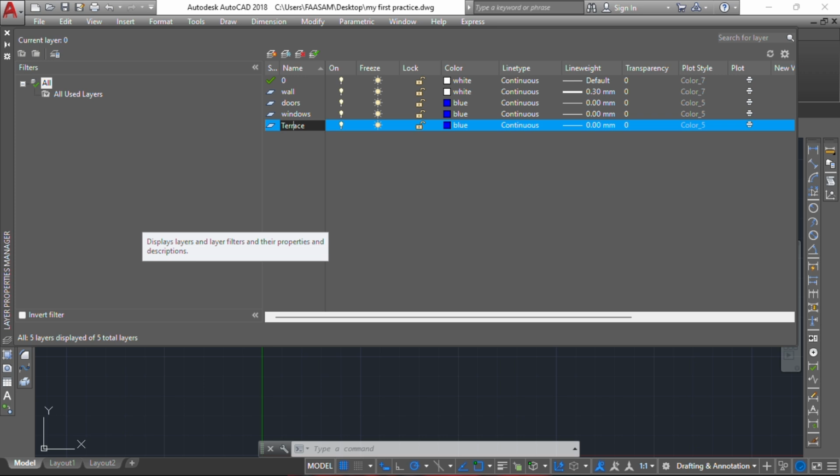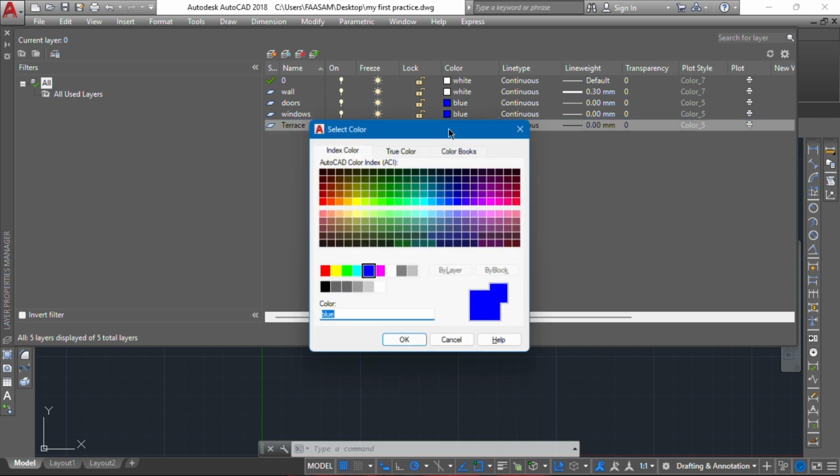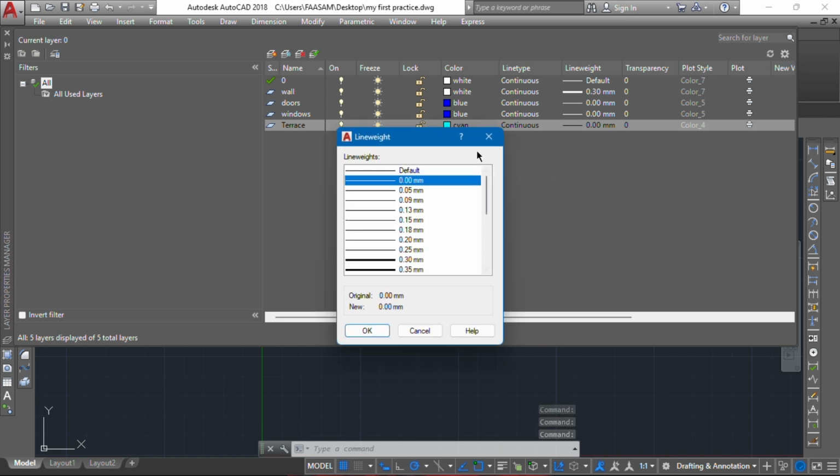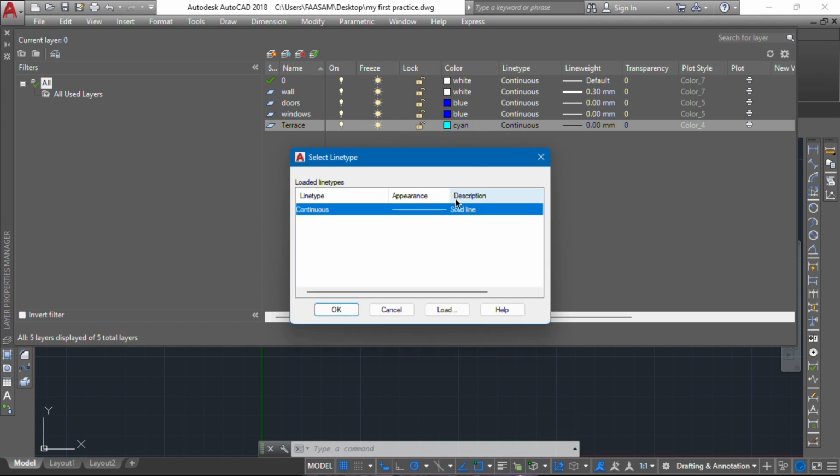That place does not usually have a wall. It's more or less like a beam or cantilever. So on the plan, you just use a hidden line to differentiate that. So let's change the color. Let's give it some kind of light blue, cyan color, and then let's change the line, not the line width, the line type. Now we need something like a hidden line, or should we say broken line, but we don't have it here.